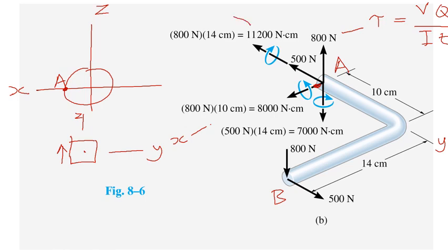That's the shear due to the torsion here. And this is giving you tau is equal to T R over J, where T is the torque, R is the radius, and J is the polar second moment of area. And that gives you this tau here, which is tau due to torsion. So this is tau T, right? Torsional stress. On the left side here it is upwards, therefore you have complementary shear on the other three surfaces. This is downwards here, right? Then you have here to the left, and here to the right. Okay, so that's all tau due to T.